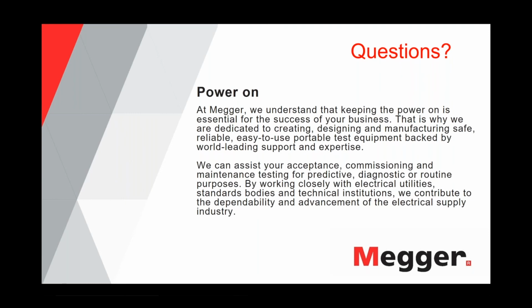What is the ratio of increase of the tan delta per year in the XLPE type of insulation? It ties right into what I just said. There is not a particular increase per year in the tan delta that is known, because it all depends on how quickly the aging will proceed in the cable insulation, and that depends on many circumstances. Okay, so there is no